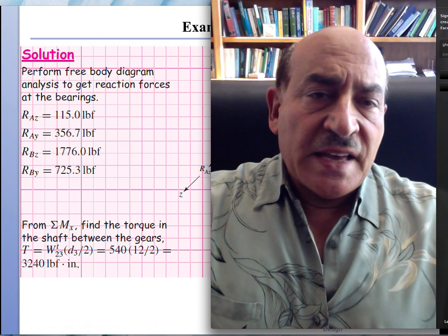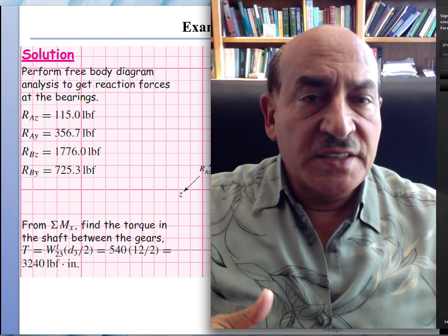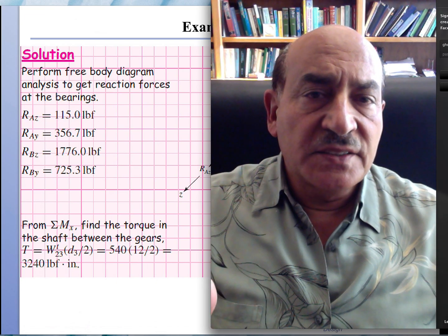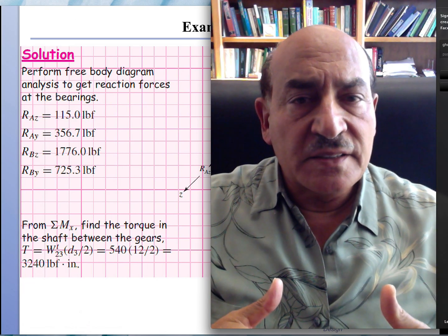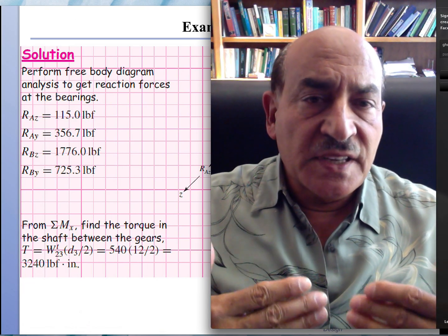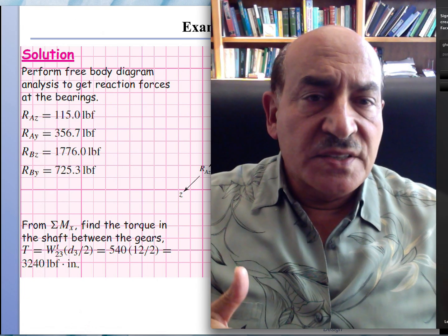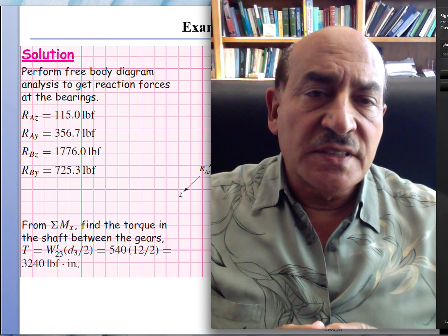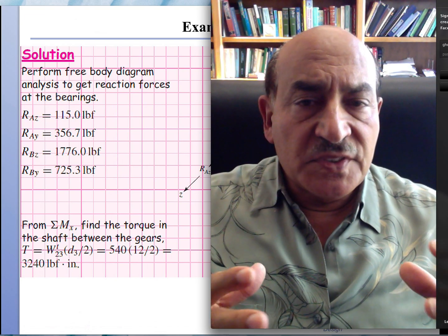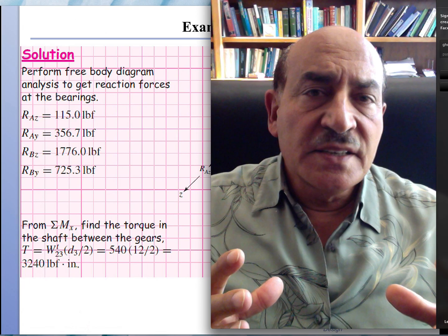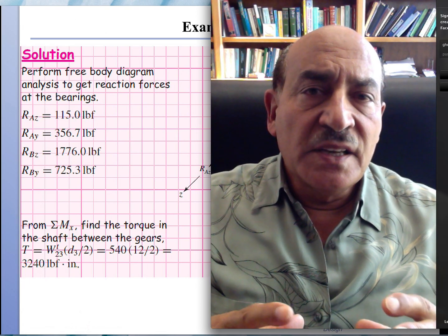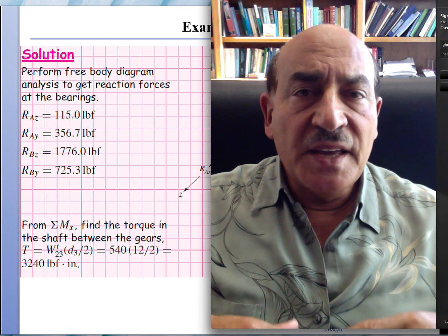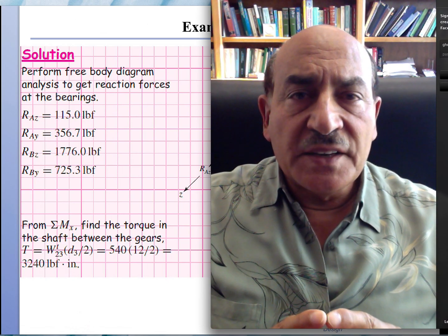And we note that we have to work with two planes because one force is coming in the radial direction, and another force is going out of the plane, which is in the tangential direction. So we must construct the force system, which is the free body diagram. From the free body diagram, we will get the information, and we will produce the shear force diagram, and then we will produce the moment diagrams.